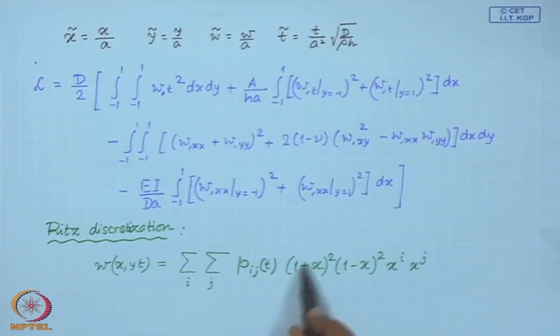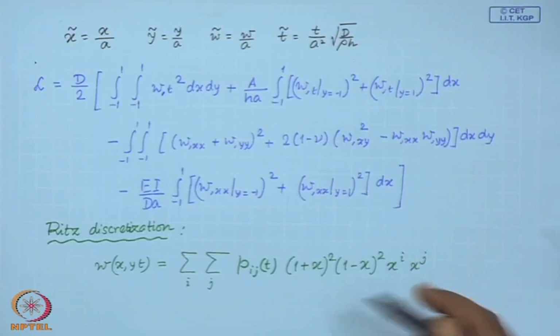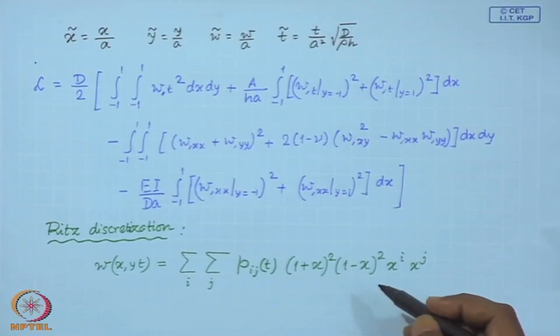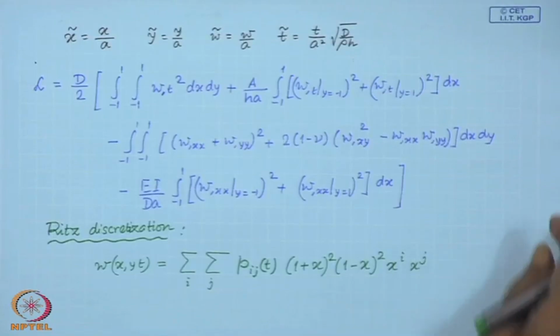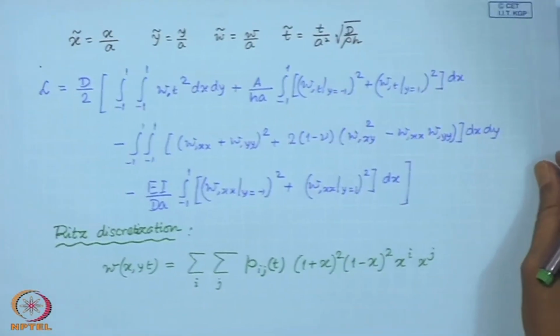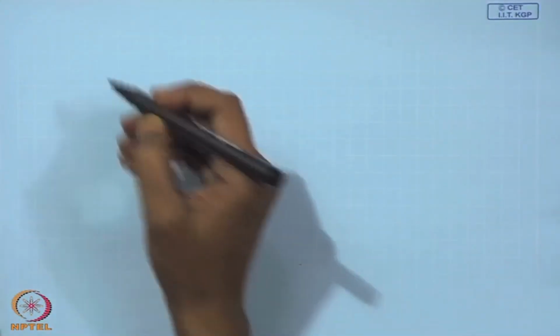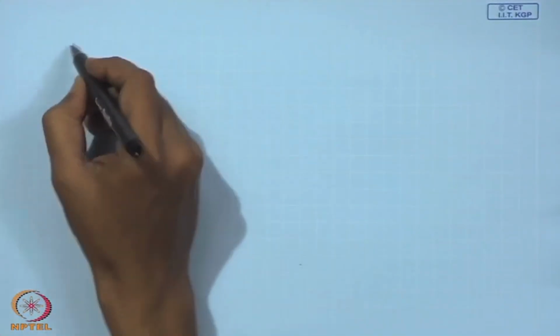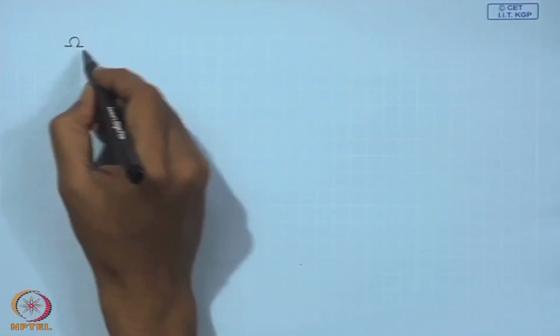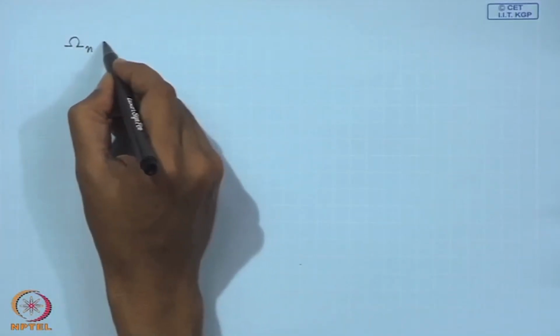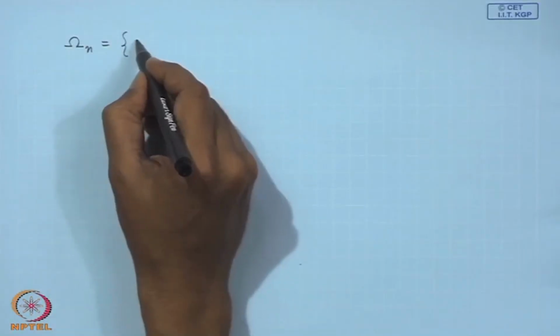You can see that it starts with quadratic in x at both boundaries, so that the displacement is 0 at x equal to -1 and +1, as well as the slopes are 0 at x equal to -1 and +1. If you use this expansion in the Lagrangian, discretize and finally solve for the eigenfrequencies, they are obtained as non-dimensional numbers.